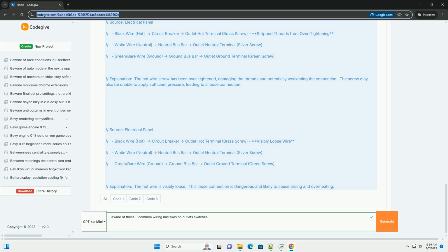It is always energized. Wiring methods refers to how wires are connected to devices. Common methods include terminal screws: wires are wrapped around screws on the device. Push-in terminals, or back wiring: wires are pushed into holes on the back of the device. These are generally less reliable than terminal screws. Wire connectors, or wire nuts: wires are twisted together and capped with an insulated connector.